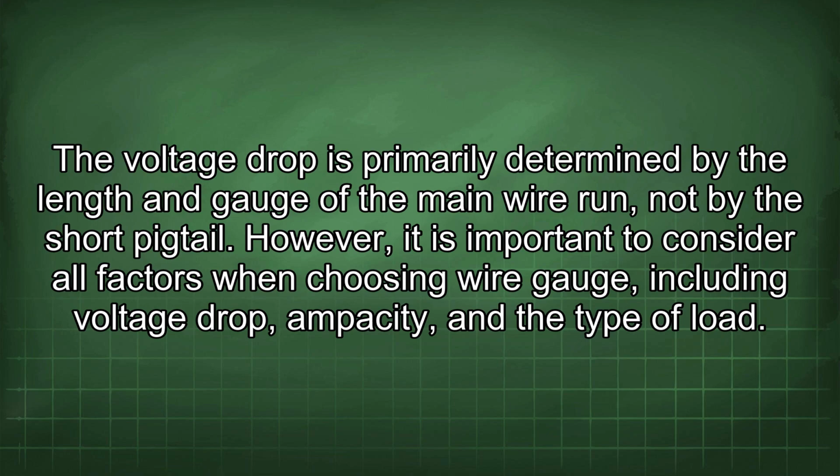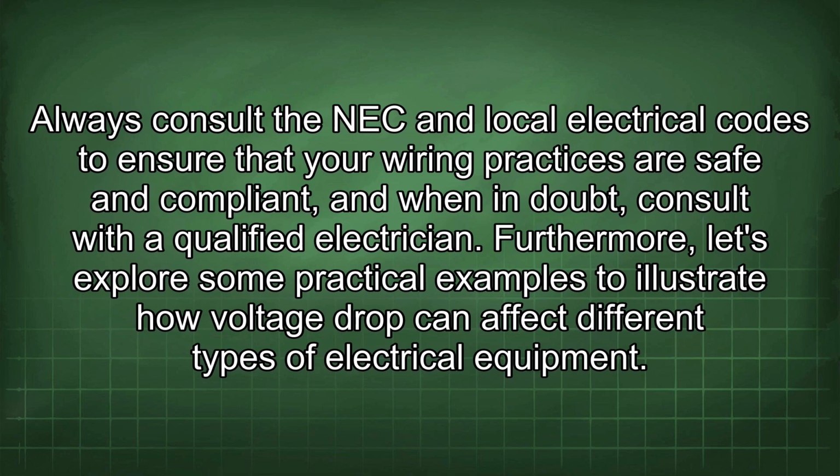However, it is important to consider all factors when choosing wire gauge, including voltage drop, ampacity, and the type of load. Always consult the NEC and local electrical codes to ensure that your wiring practices are safe and compliant, and when in doubt, consult with a qualified electrician.